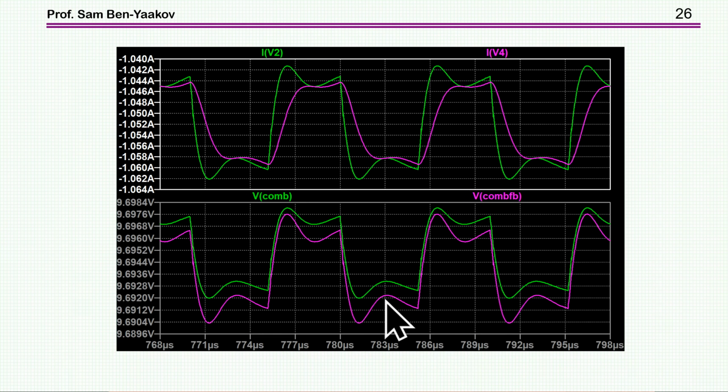For this, if I would like to lower it, I need a much larger electrolytic capacitor, of course. It has nothing to do with the oscillation. And obviously, if I would like to eliminate the injection into the source, I need a larger impedance to handle this lower frequency.